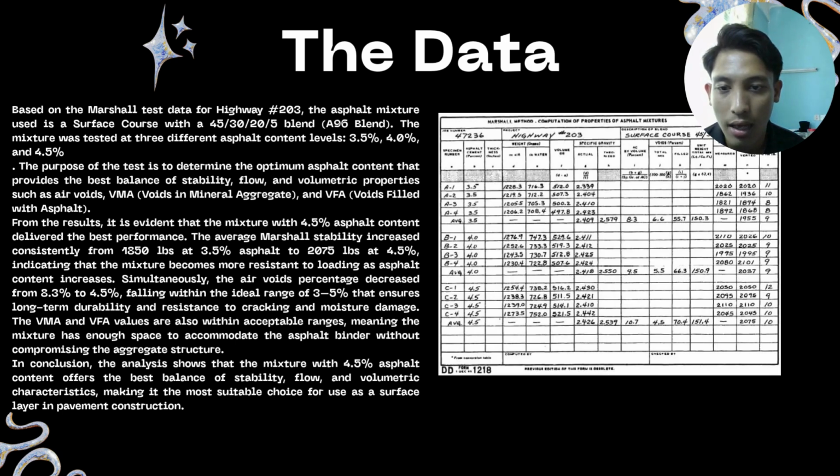The VMA and VFA values are also within acceptable range, meaning the mixture has enough space to accommodate the asphalt binder without compromising the aggregate structure.